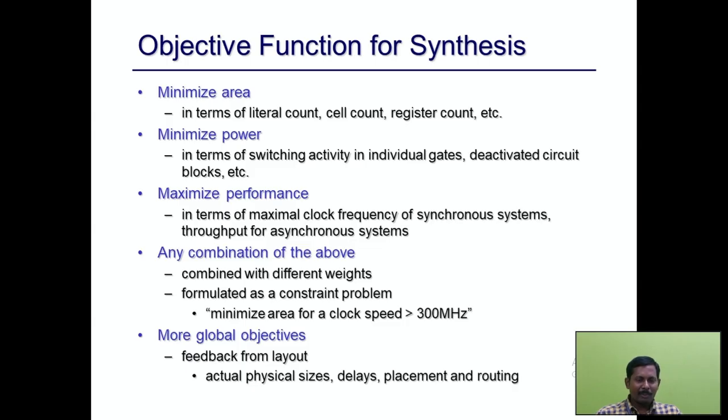Next, we need to maximize the performance of the design or entire system, in terms of the maximal clock frequency of synchronous systems. So we need to increase the clock frequency. Blindly we can't increase the clock frequency, so it needs to be validated in each and every block present in the entire system with timing analysis.